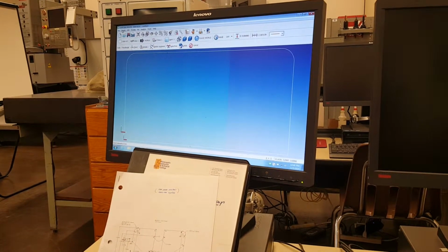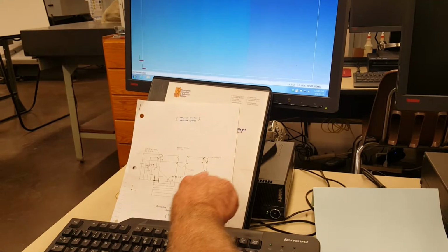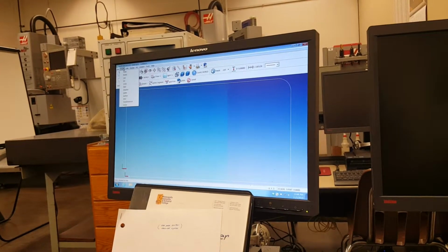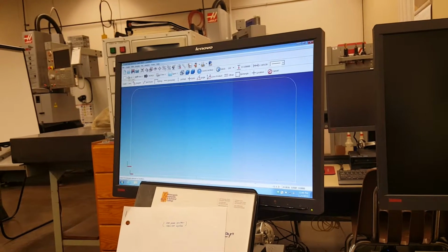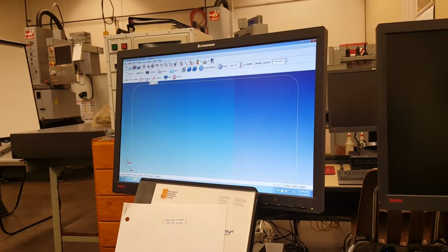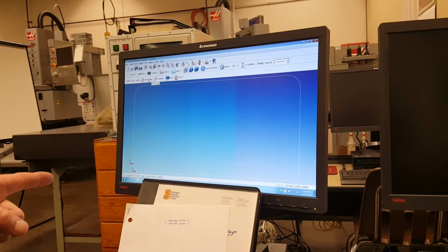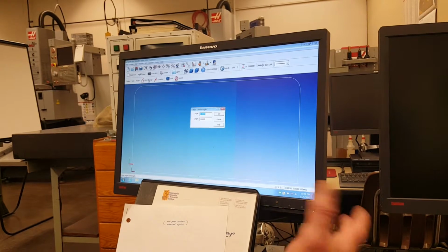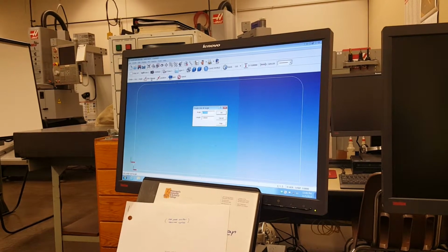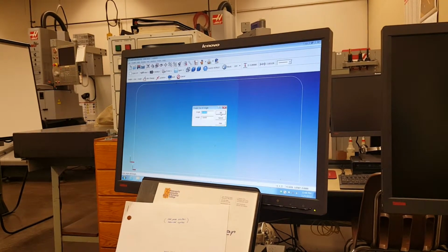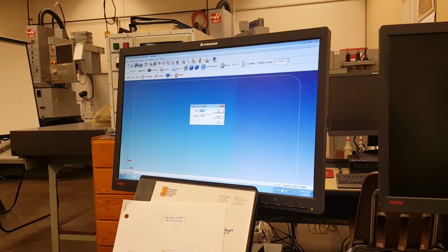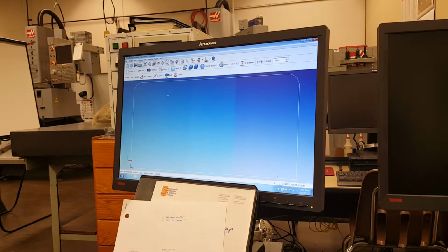Now, I'm looking at these angular lines, and what we can do for that is create a line at an angle, but look what's going to happen. It says select an element location angle 0 length 1 info change. Do we know the angle there? No. So I can't use that to create an angular line. So what I'm going to do is go ahead and create some points, because it's telling me where those lines start on the drawing. So I'm going to cancel that. And I'm going to go back.